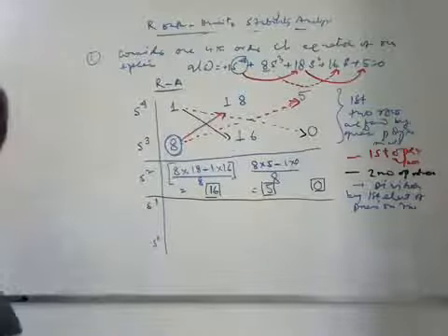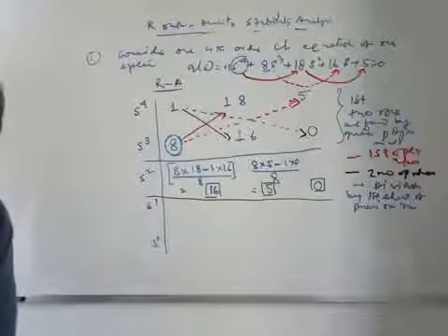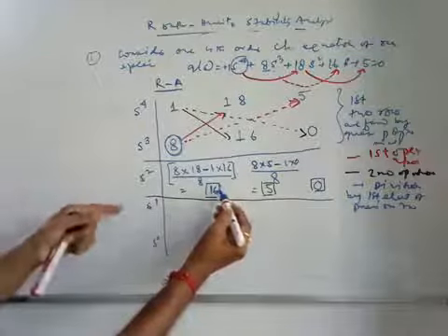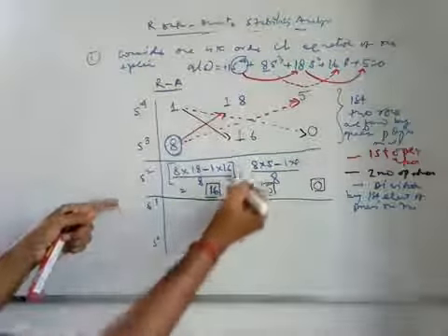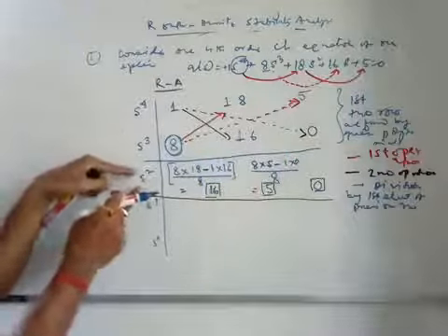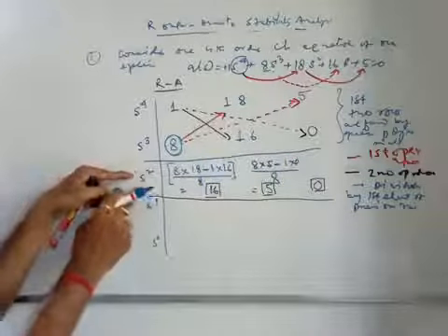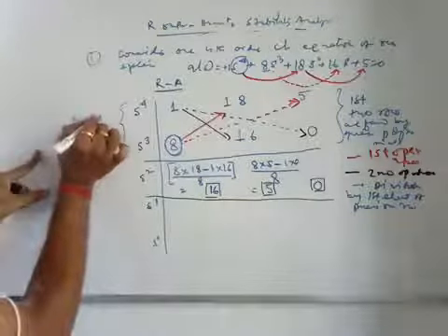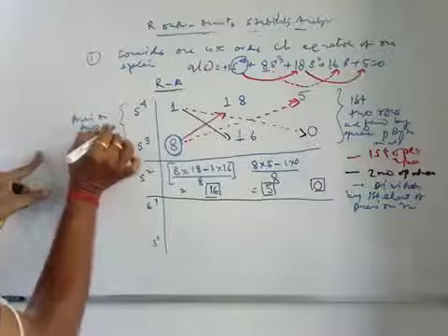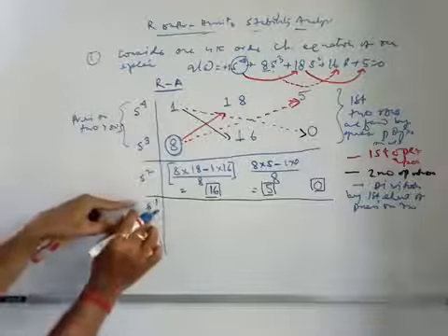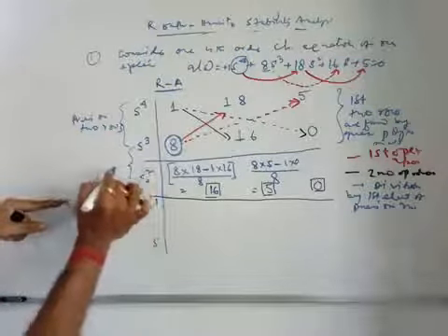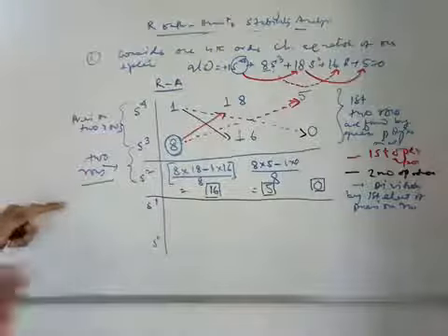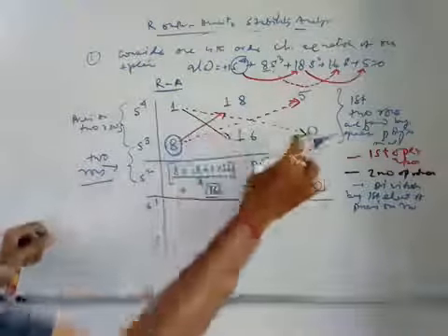You see, with the same procedure, you have to take the previous 2 rows. When you constructed the s to the power 2 elements, you considered the previous 2 rows. So when you consider s to the power 1, you have to consider these 2 rows. The elements are like 8, 16 and 0, and 16, 5, 0.